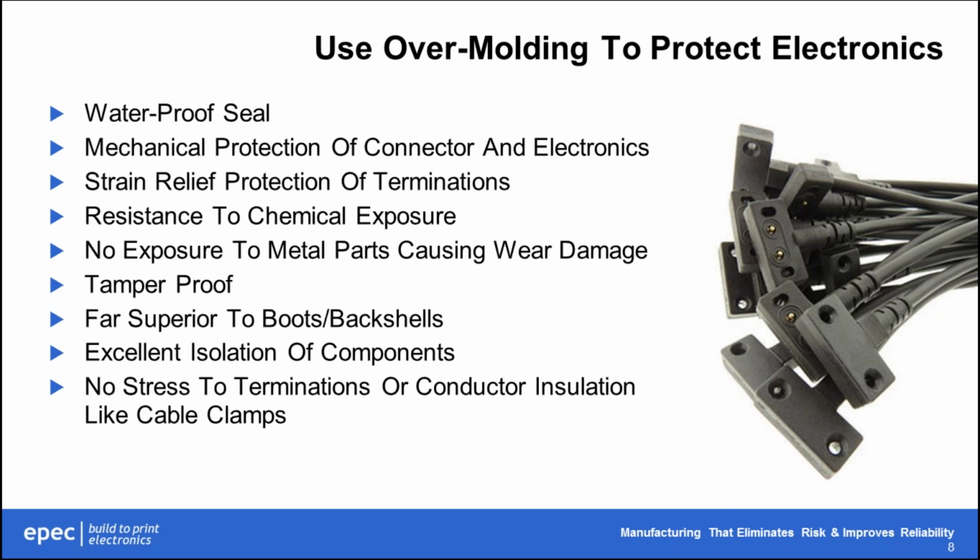If you do them properly, an overmold will isolate the components from the outside world, as well as isolating them inside the overmold cavity. The protection that it provides will eliminate any possible wear damage to any of the components and prevent the cable from leveraging any of the termination points and causing a premature failure.